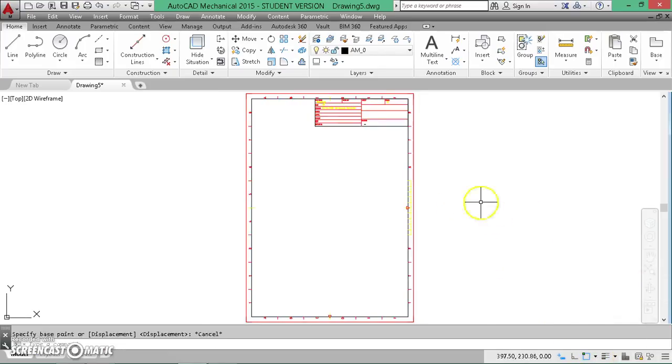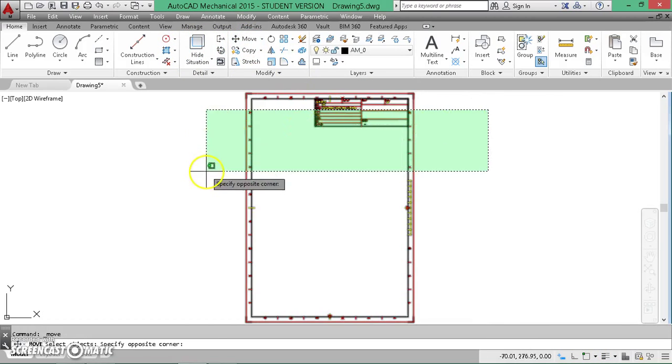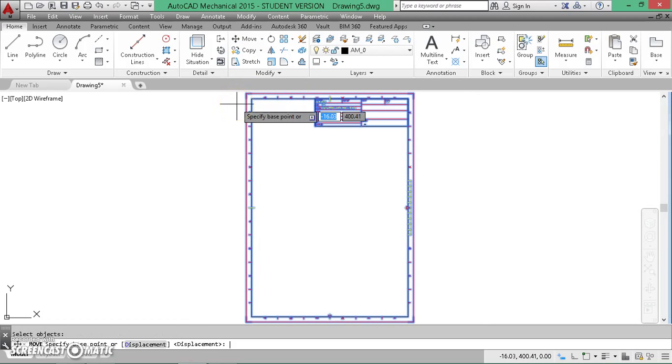So let me press escape and show you, if you don't know how to get to the options of 2D snap. This is on the status bar. This shows that 2D snap is on. If I switch it off and try to do the same thing, you will note that I am no longer able to see any points or any of those small green rectangles. So now I am completely manually choosing my points, right? Okay, so let's press escape again.